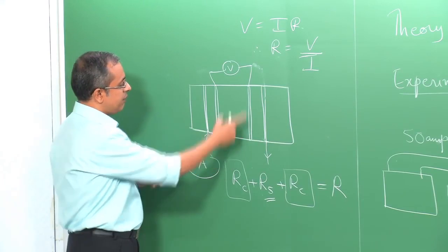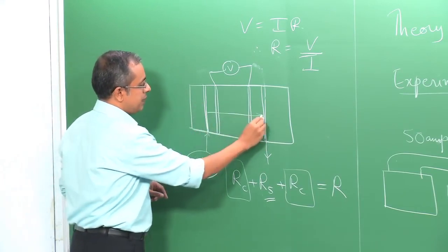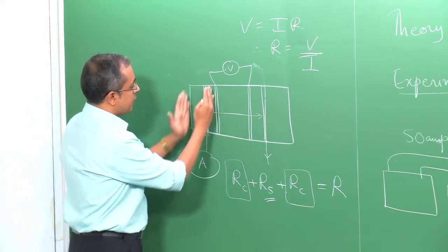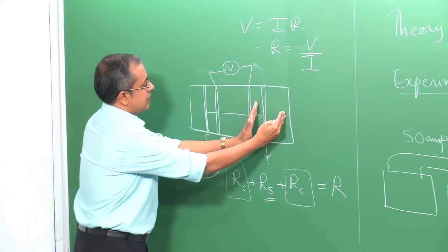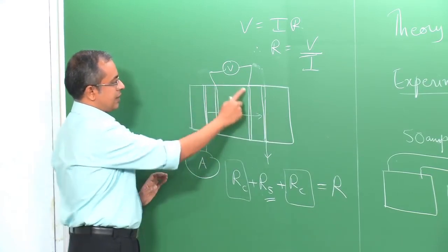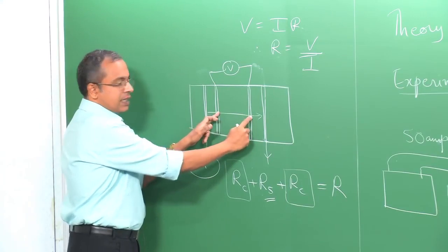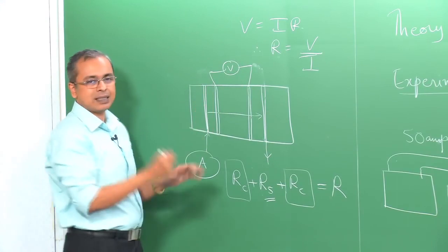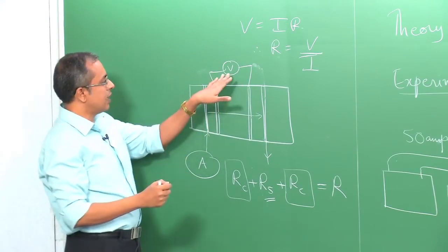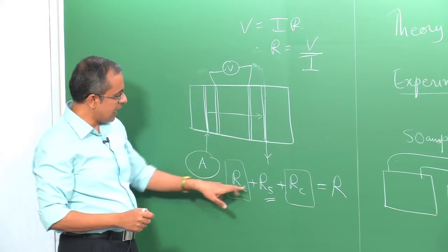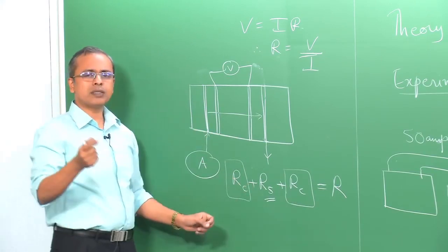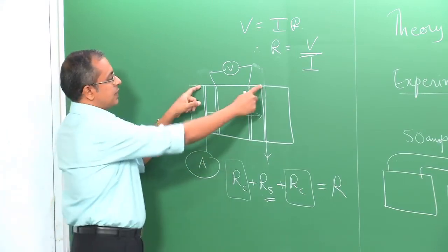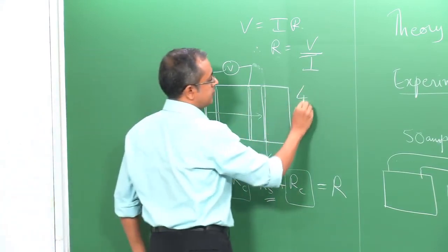But the way we are running, the current that flows through the circuit is the same. So, the same current goes through the entire circuit. It is just that we no longer bother about the behavior of the sample on this side and on this side. We only look at the behavior of the sample here, and in this location we know the current that is going through, and the contact resistances involved with this measurement process are extremely tiny. And therefore, you eliminate the contact resistance problem. You still have two contact resistances, but they are now extremely tiny. They are 3-4 orders of magnitude smaller than what they were when you had a two probe measurement. This is called a 4 probe measurement.